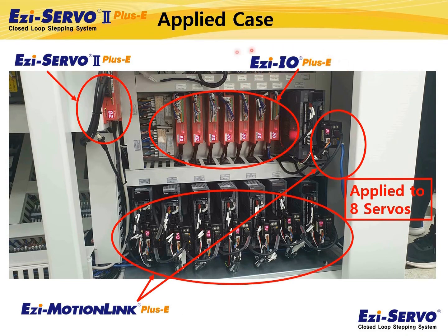Since I/O is connected at the same time, if you use Motion Link for such a small machine, you can control servo, step, I/O through Fastex API through one Ethernet network without a separate motion board for AC servo. Therefore, it is possible to save the cost by removing unnecessary motion board and reducing wiring.